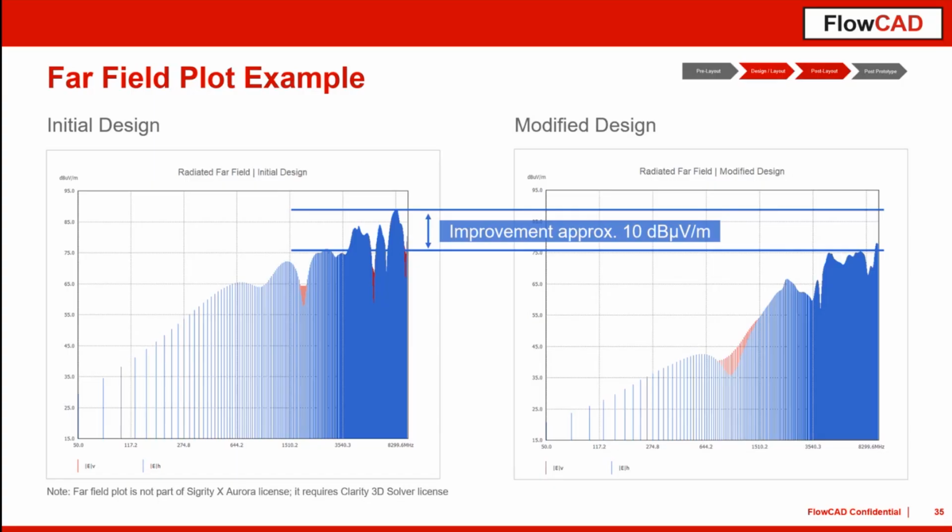And if you really can avoid such things by checking, for example, the impedance, move them around, move them away from these split planes, maybe attaching some additional ground stitching vias so that the return path has a better way to directly follow your signal current, then you are fine. And I think that will significantly increase the robustness of your complete design.